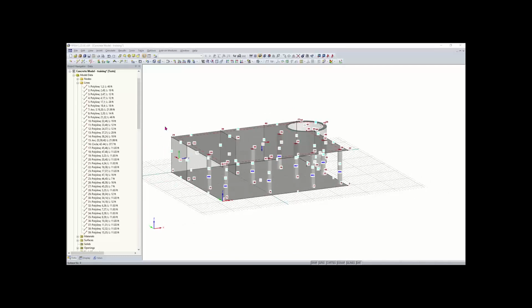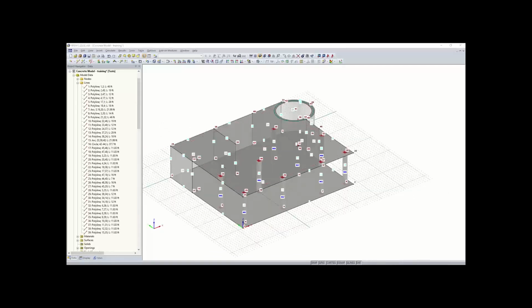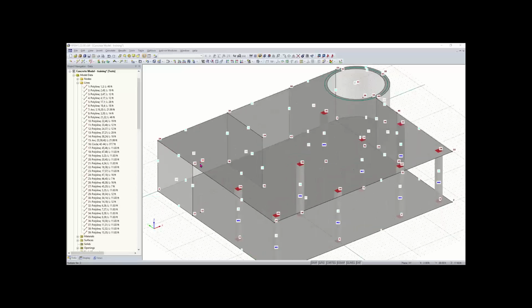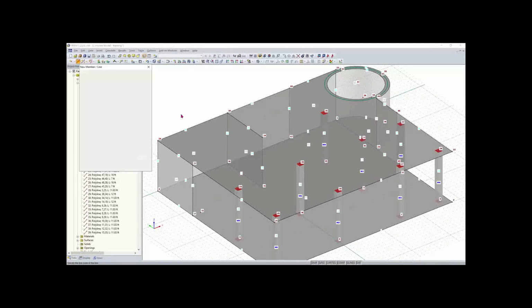And so the last thing we need to do for our model data is just add in this downstand beam. So there will be a downstand beam from the edge of this wall here, node 37, all the way to this column, node 35. This node 33 here is not needed, so I'll select that and delete it. And to add in this beam, I can simply repeat what I did for the column.